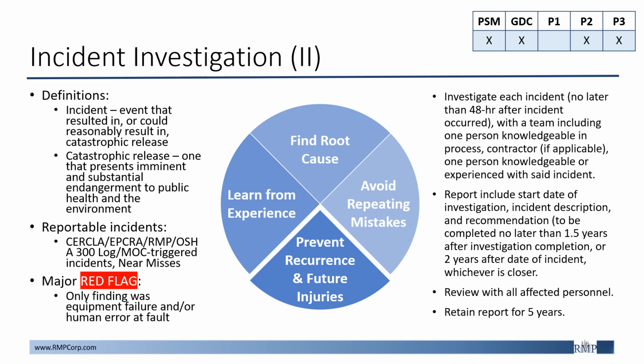The incident investigation report must include the start date of the investigation, incident description, and recommendations, which is to be completed no later than 1.5 years after investigation completion or 2 years after the date of the incident, whichever is closer. The incident investigation should be reviewed with all affected personnel, and the report must be retained for 5 years.